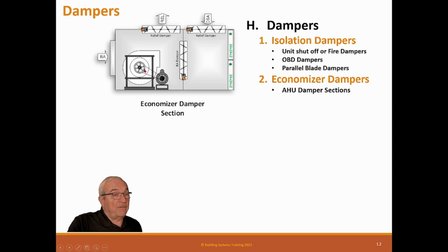If you don't have a fan here, now the supply fan has to pressurize the space to be able to blow it through here. Now these are on economizers that would always blow the doors open, right? So you take the supply fan to suck in 100% outside air, pressurize the space, blows the outside air doors open, and to get the air out of here. So you either need an exhaust fan, a fan up here, or a return fan to make sure the space is the same.